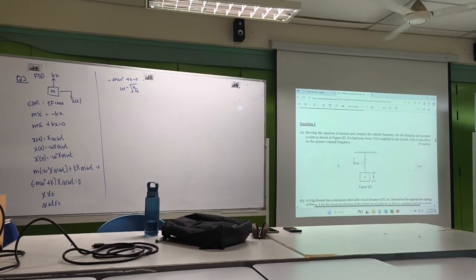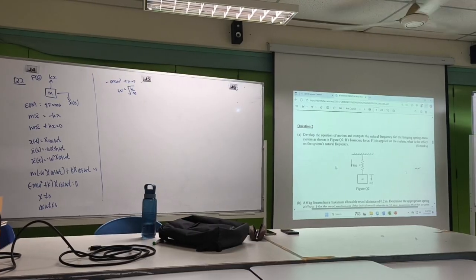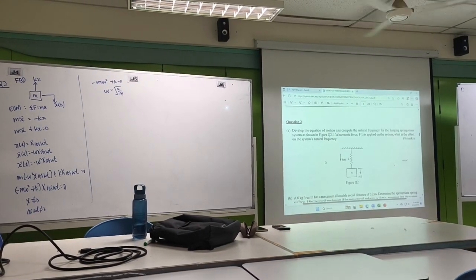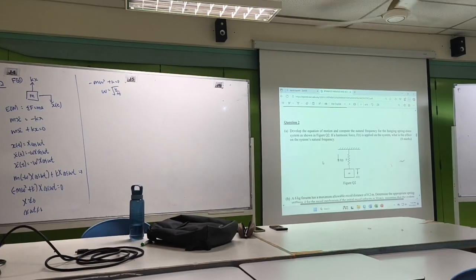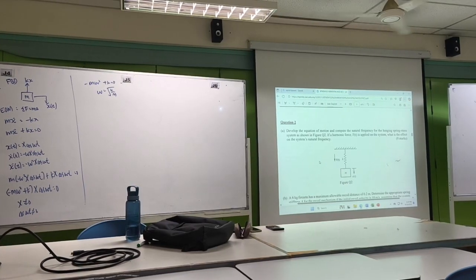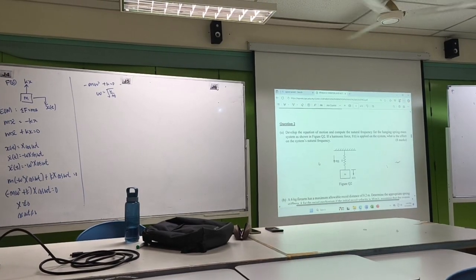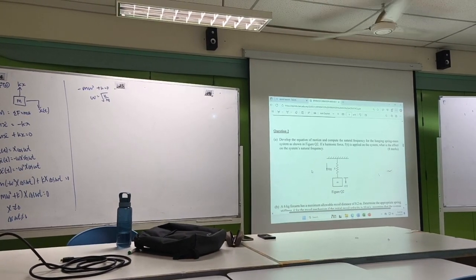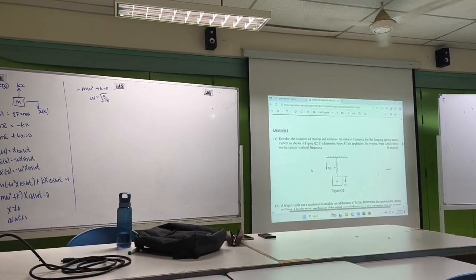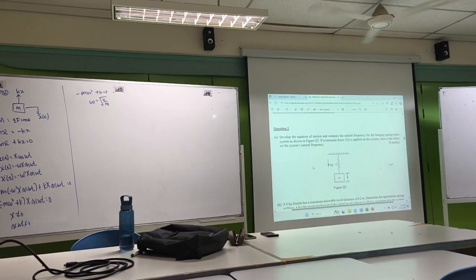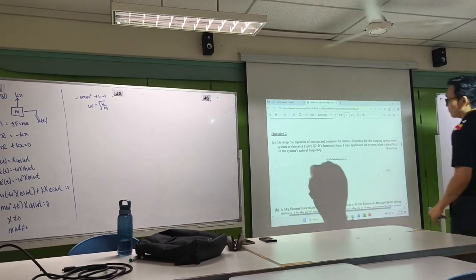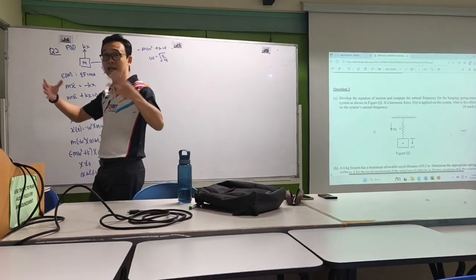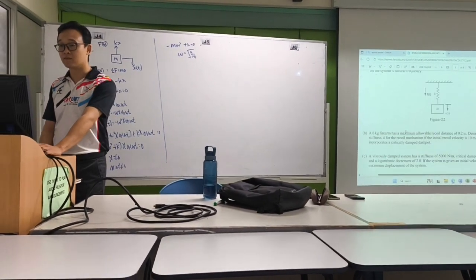That's why in the equation of motion we don't need to include the external force in our free body diagram. It won't affect the natural frequency. So don't say that if you apply the force, the natural frequency will become higher. A lot of students will do that. Natural frequency is a system characteristic, not affected by external influence.